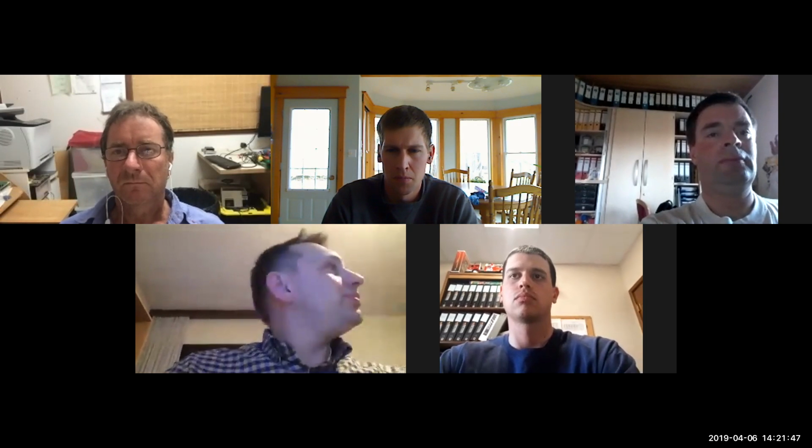I also got, can I show it? Do you see it? Yep. A box of F9s, 20 pieces. And I have successfully put two together. The first F9 is running as the car rover, and I've connected the second F9 to the first. That's called the moving baseline. The first F9 puts out RTCM messages to the second one, and the second one also calculates its position. It's very easy to make a dual antenna system with it. The only problem is to get all the messages together and write it back to AgOpenGPS.